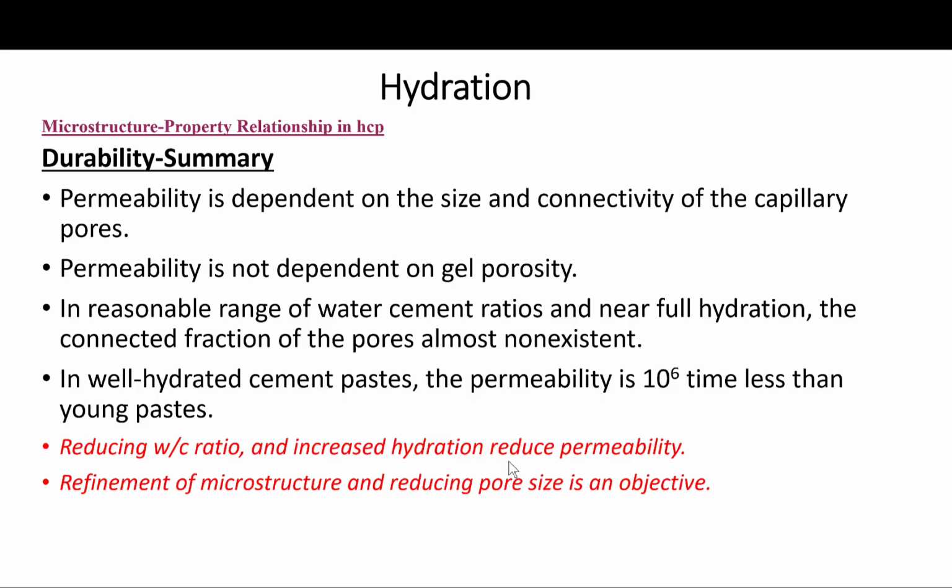So just with that, I will mention a few points. Again, water cement ratio controls porosity of the hardened cement paste. High quality concrete consists of low water cement ratio and low permeability. A low water cement ratio and adequate curing are key elements in concrete technology. So remember, keep that in mind, please.